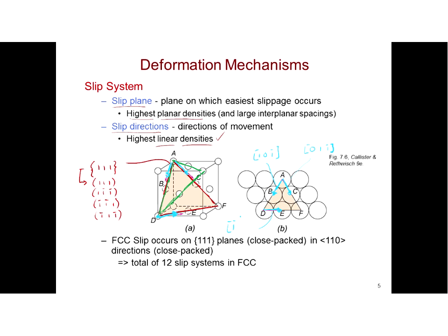+1, right? And how much in the Z? 0. Right. Good. So those are sets of directions, and they in fact are a family of directions. Depending on how you look at the unit cell, where you choose your origin or what you call your X, Y and Z axes, these directions are all basically the same. They're moving along the same linear density. So they form a family of directions, and that family is the 1, 1, 0 direction. So those are the close packed directions.